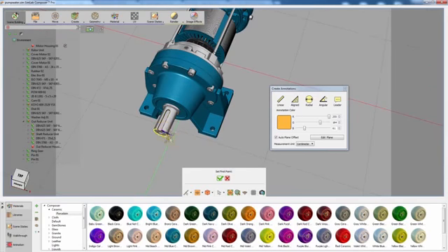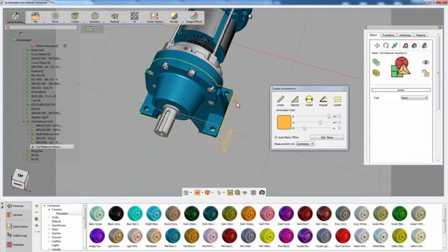To measure the length of the rotating rod, select the Linear Measurement tool. Then change the picking type to Center of Curvature, since the ends of the rod are made of loops and not edges, and click on the loop at the far end of the rod to set the first point. Then click on the opposing loop to set the second point.